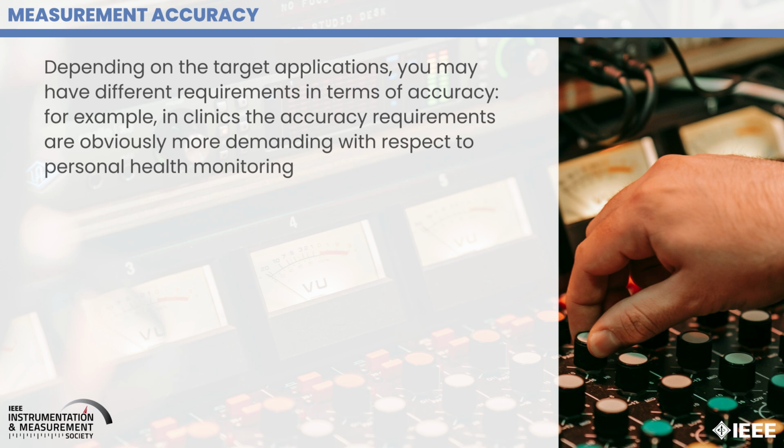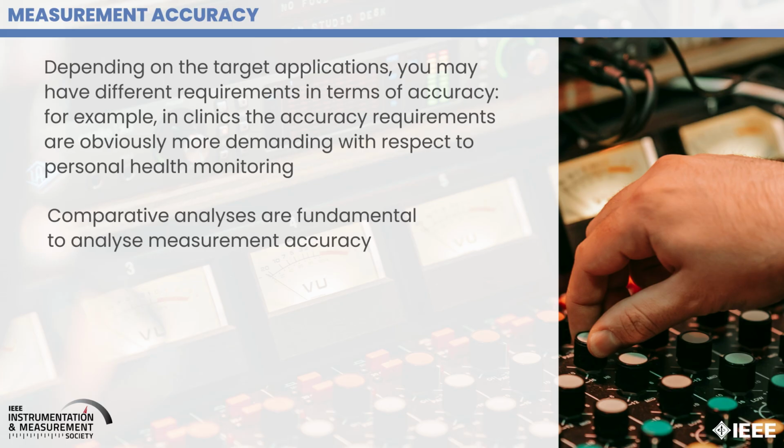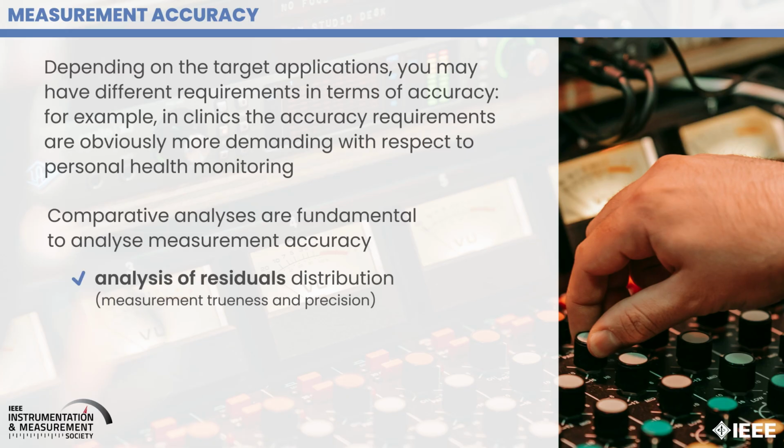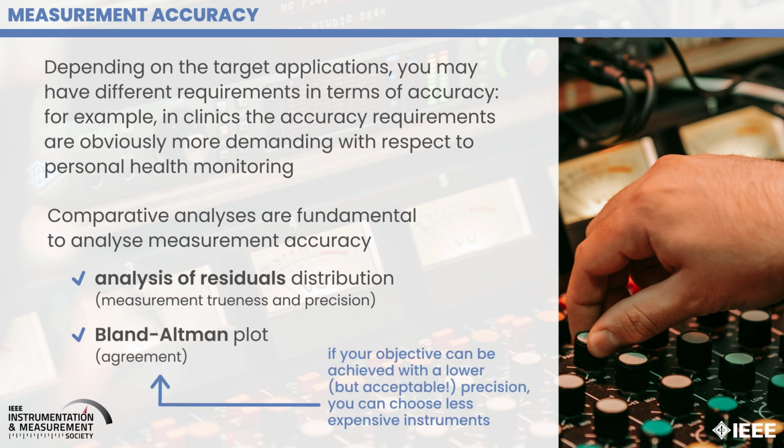Depending on the application, you may need different requirements in terms of accuracy. Comparative analyses are fundamental to evaluate measurement uncertainty and hence choose the most suitable sensor. As said before, the mean value and standard deviation of residuals are related to the measurement trueness and precision, respectively. Moreover, also outliers in the measured values can be identified. Additionally, the Bland-Altman plot allows you to evaluate the agreement between two measurement methods.